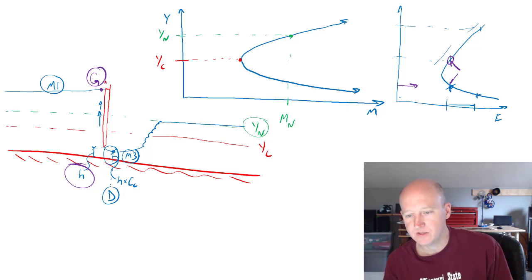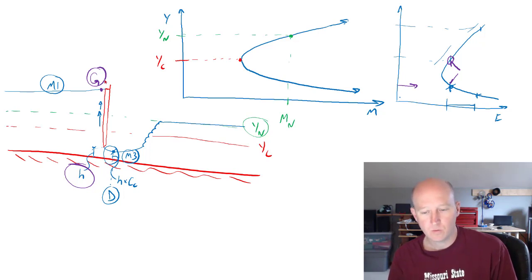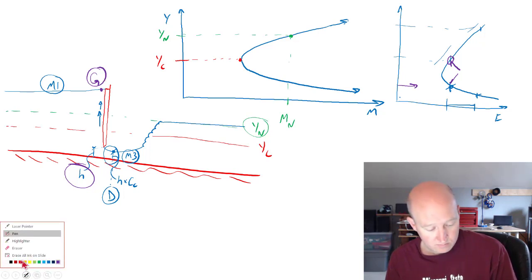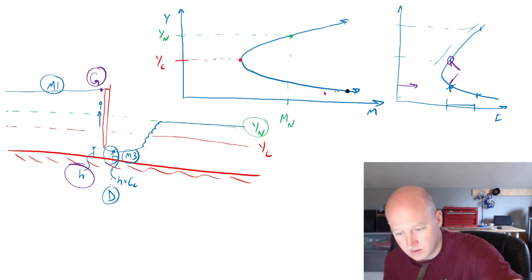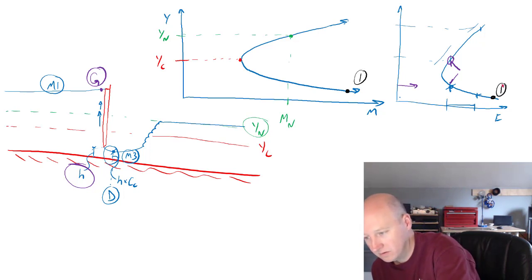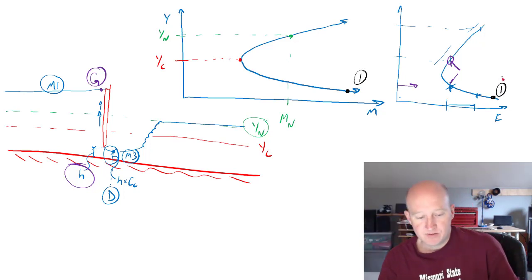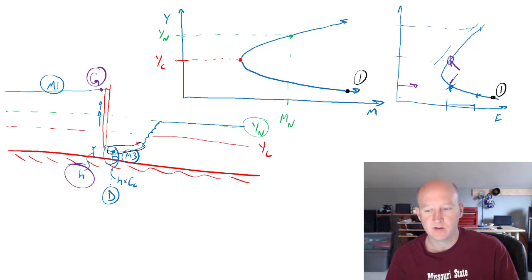So now what we need to do is take a look at what happens as the gate moves with the specific force. So let's say that we have the gate really, really low. So let's call this scenario 1. So the gate's really low. This is scenario 1. And so what's going to happen is during this section of the M3 curve, we're going to be burning off more energy than what we're gaining because the slope's relatively mild.